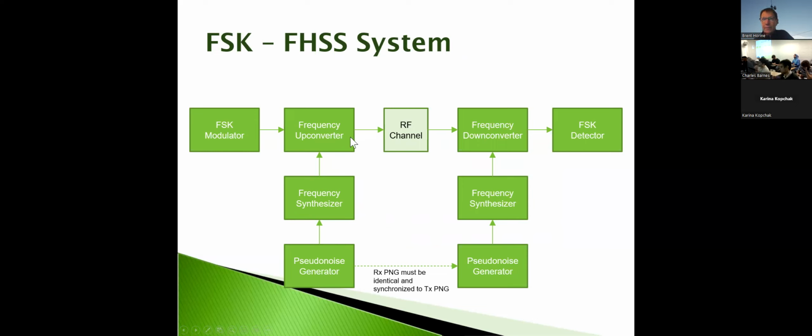But you're still looking at the energy in one of those deviations of the symbols. So in FSK, remember that in a binary FSK system, we're sending a bit 0 and a bit 1, and each of those corresponds to a different frequency deviation from the mean frequency, right? So you're aggregating or summing up the energy in those frequency bins during that whole symbol time period, regardless of where we're hopping.